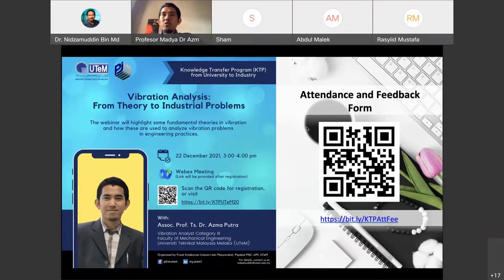Yeah, in vibration we use what we call an accelerometer. From the name, it measures the acceleration, and then with the signal processing in the analyzer, we can get the velocity as well. The analyzer will perform the integration, in theory, from the acceleration to get the velocity. We have to integrate. So we use an accelerometer.